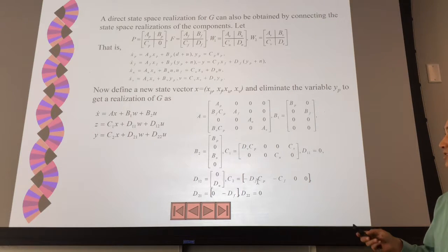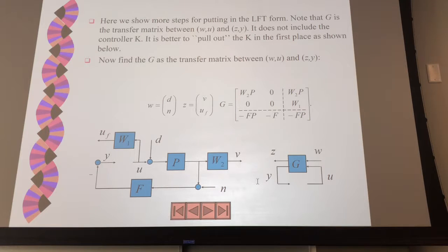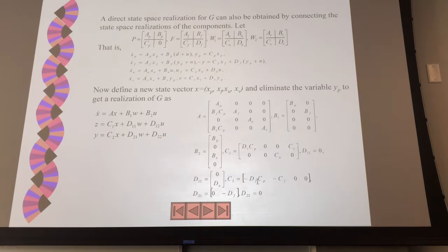Okay? Then you stack all these things together, you end up with a state space like this, which is the same as this format. So you may ask, is this minimum? The answer is no, it's not minimum. Writing this format is probably for convenience. So whenever you see this format, you know that these matrices are from this type of realization. By individually realizing each one, of course, each one is minimum. Put together, it may not be, because of other connections.